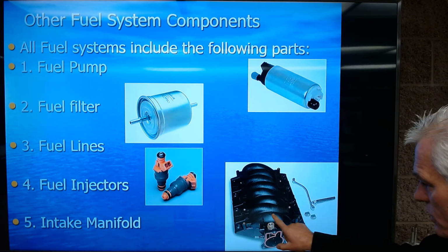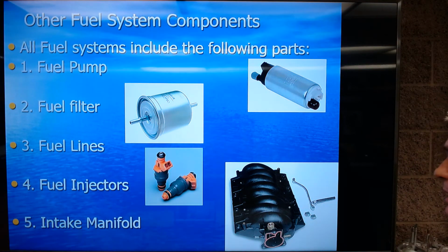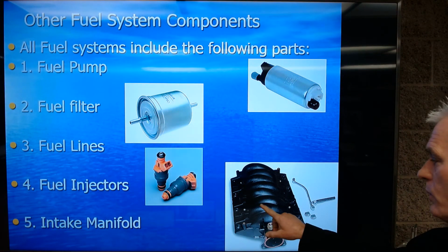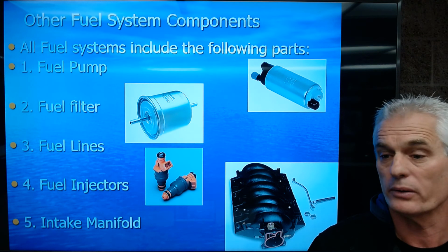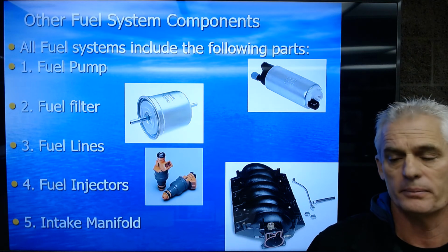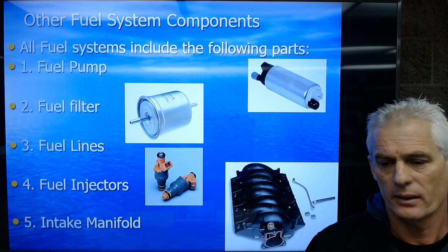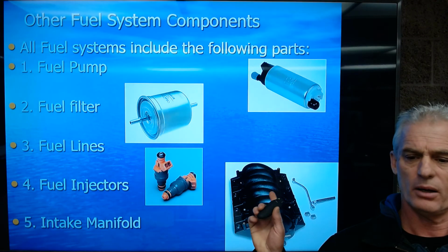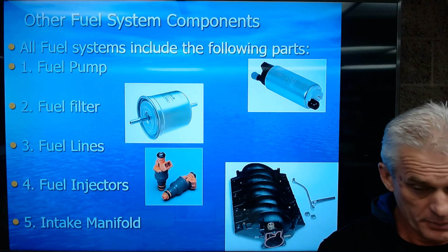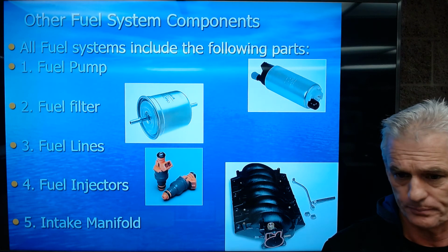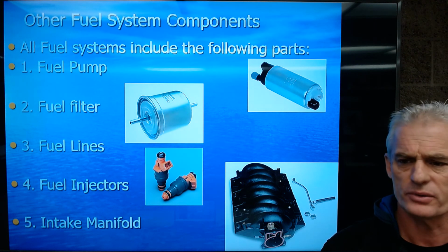What's going on is we're not only distributing air and fuel to the right cylinder at the right time, but we're putting the air through a tube with a certain length. A longer, smaller tube tends to build torque, and a shorter, larger tube tends to build horsepower. So we can do things to help the power of the engine based on intake manifold design. Just an FYI, something mechanical engineers look at really carefully. I think that's it. So that's a little bit on fuel systems in cars.